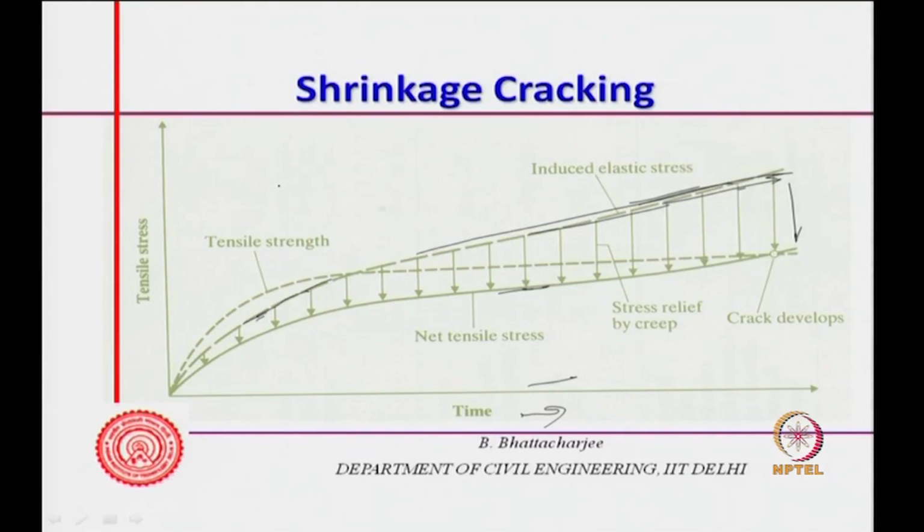Curing has not been done properly. One might have even used an accelerator to accelerate the strength gain or something similar. This scenario, where curing is not proper, is seen much in hot dry desert climates where relative humidity is very little, or in a composite monsoon climate during the hot dry season. Shrinkage will increase with time, and tensile strength also increases with time, but since it is sustained and restrained, there will be some relaxation.